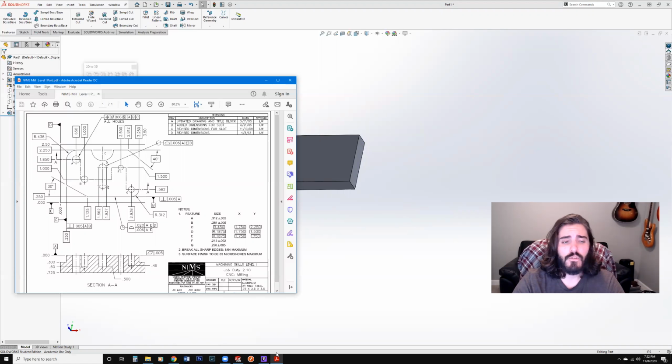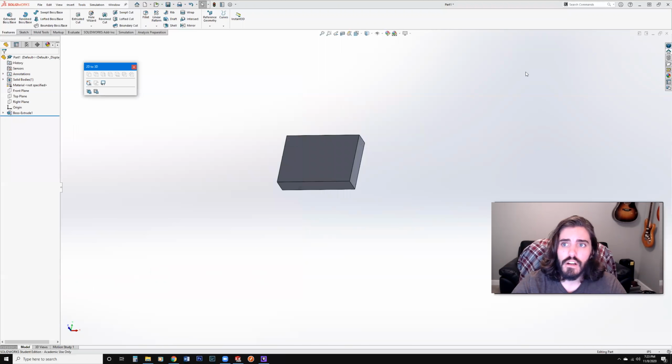This is also really helpful if you're working with somebody who has a different 3D CAD modeling software. So if I was working in SolidWorks and you were working with Inventor, the way that you guys can communicate with each other might be in a 2D environment with the DXF or DWG. We used the DWG today. You can also save this out, as I can show you as well.